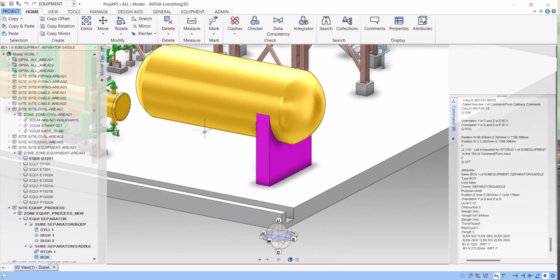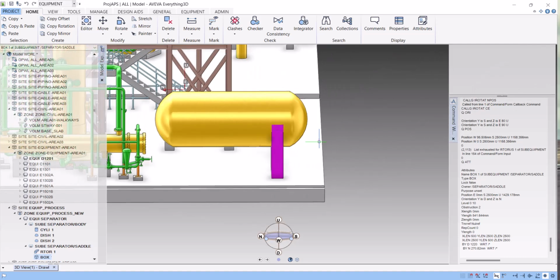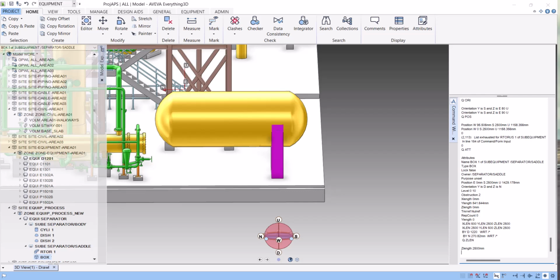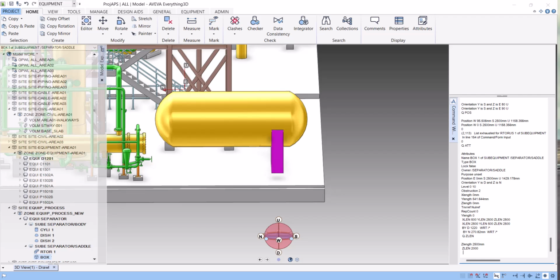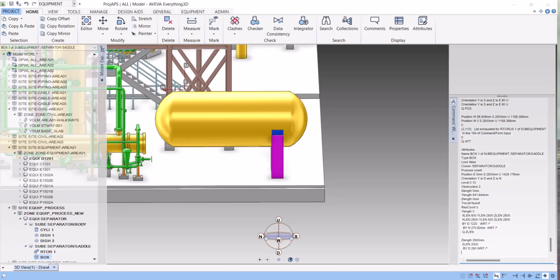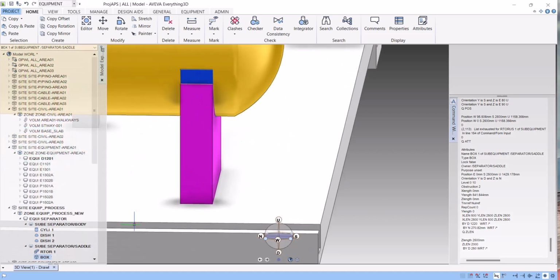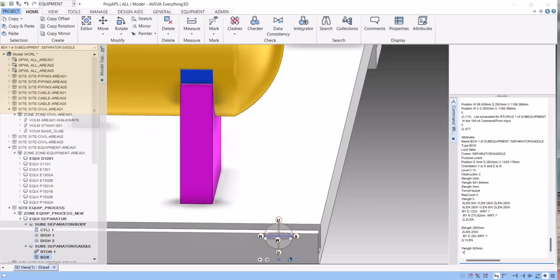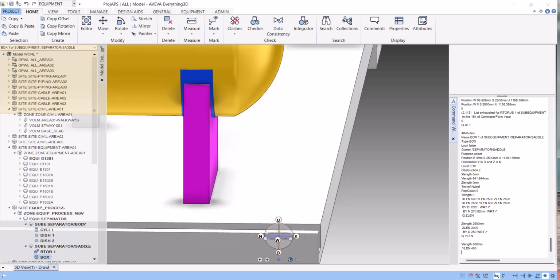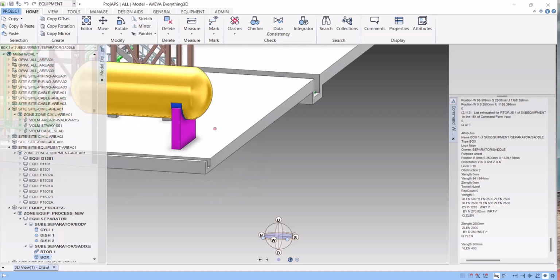Now we will reduce the height of this box. You click Z length, it is 2.5 meter. Now we will type Z length is 2 meter and we will go down 50 to match the bottom. And Y length, I want 400 for better understanding.